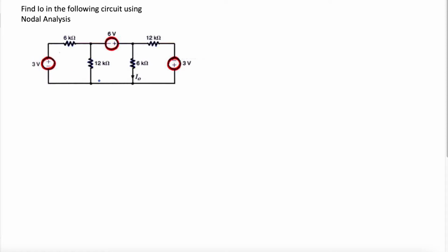If we know anything about nodal analysis, we know that we have to label our nodes, right? So we have 4 or 5 nodes actually. We have one here, here, here, here, and then this is the bottom node. These two are the same. Let's label this our bottom one. Like we usually tend to label our bottom ones as our reference node, so let's label this as a reference. And this will be our V1, V2, V3, and V4. So here we have 4 nodes, or 5 nodes actually, including the reference. Let's look at how we can solve this problem.